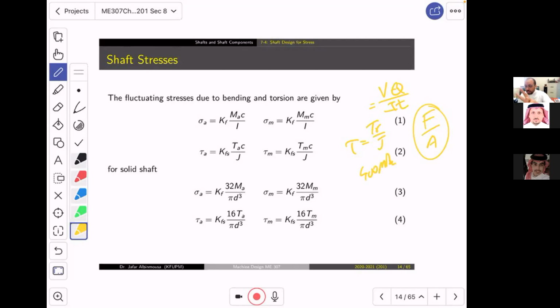So the yield in torsion will become 200 megapascal. And if you apply tau, which is 395,000 Newton meter over a small diameter, your stress will shoot up. Even if you make it a little bit big, you might get like 150 to 180 megapascal of shear, and you have only a yield of 200. You are in a very dangerous zone. So you can easily get a high shear stress from torque.